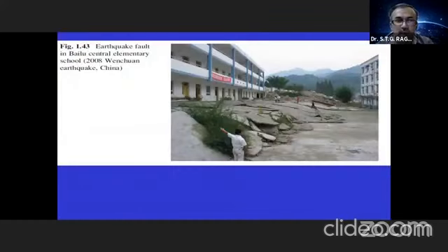And now there is also one more school building from this Chichi earthquake. You can see here, these are 2 buildings actually. This building is located on this side of the fault, whereas this building is located on the other side of the fault. During the earthquake, this portion has raised, and this portion came down. But luckily the buildings are safe. You can just imagine if the building was constructed across the fault, automatically the structure could have collapsed due to these near source features.